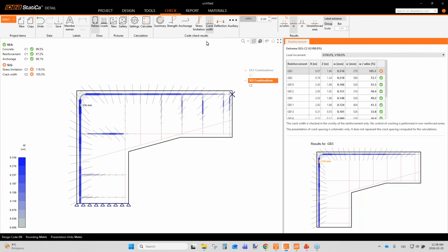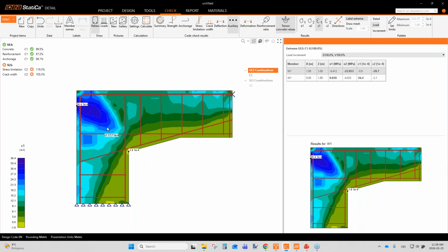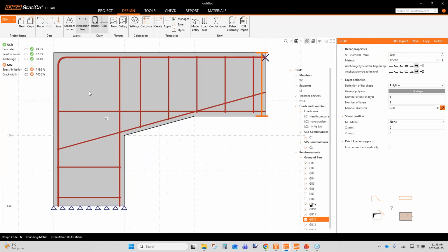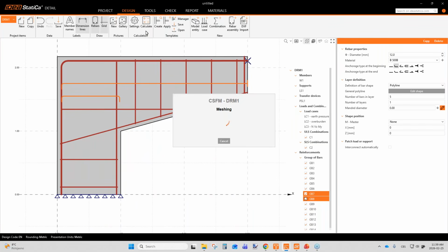So what is the recommendation? If you see that somewhere you have big tensile strains, probably there is some cracking forming, put at least some reinforcement bars, at least for detailing purposes. Even some thin reinforcement can be sufficient there to check out whether the concrete is cracking there, and so you can catch those tensile strains there. So now I have completed my reinforcement setting with these horizontal rebars, and let's calculate the model again and let's see what changes.